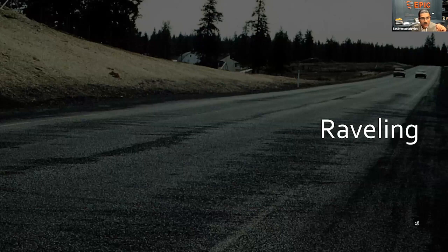Raveling. So this is going to be a pretty extreme condition, at least within this image, as you see it. So you'll see it along the center line. You'll see it along the edge of the drive aisle in either direction as well. Now, this is going to be considered a climate or a durability-based distress. And this is really going to be a medium to a high severity of a weathering condition, right? This is mainly a function of weathering. We're going to discuss weathering briefly afterwards.